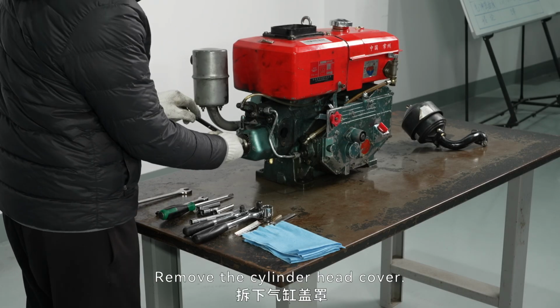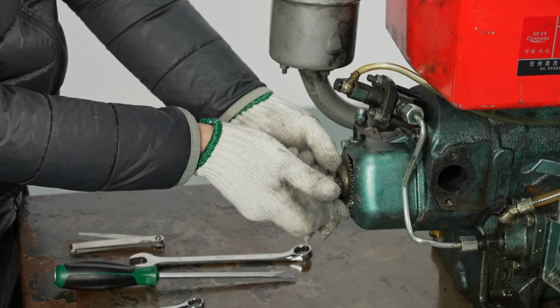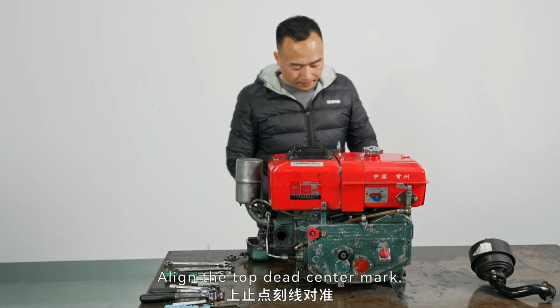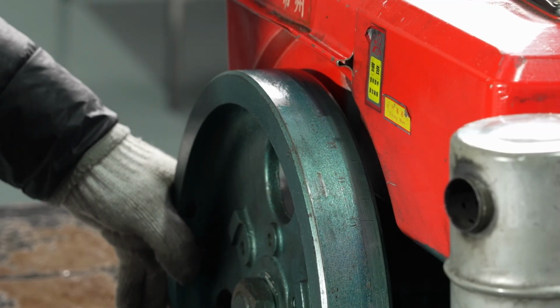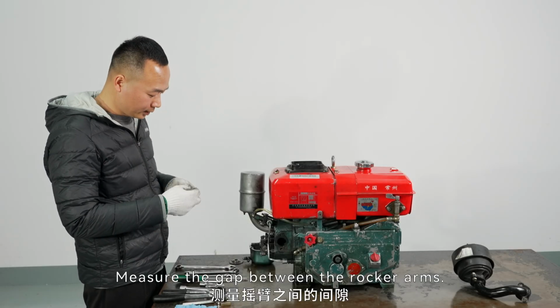remove the cylinder head cover. Align the top dead center mark. Measure the gap between the rocker arms.